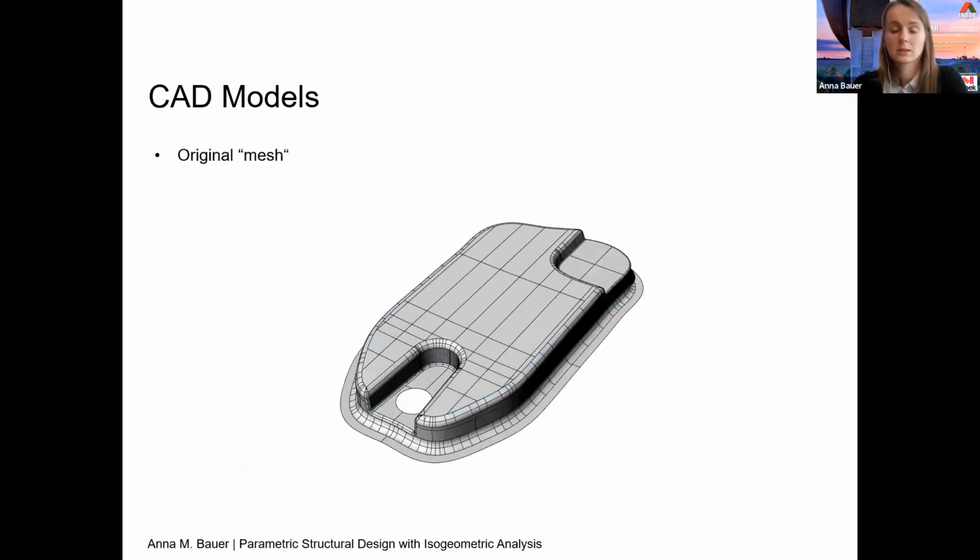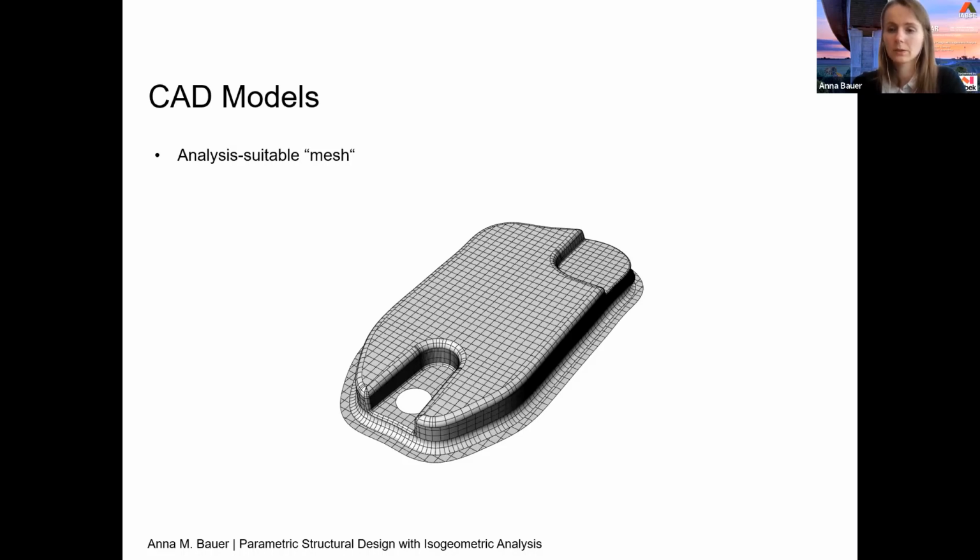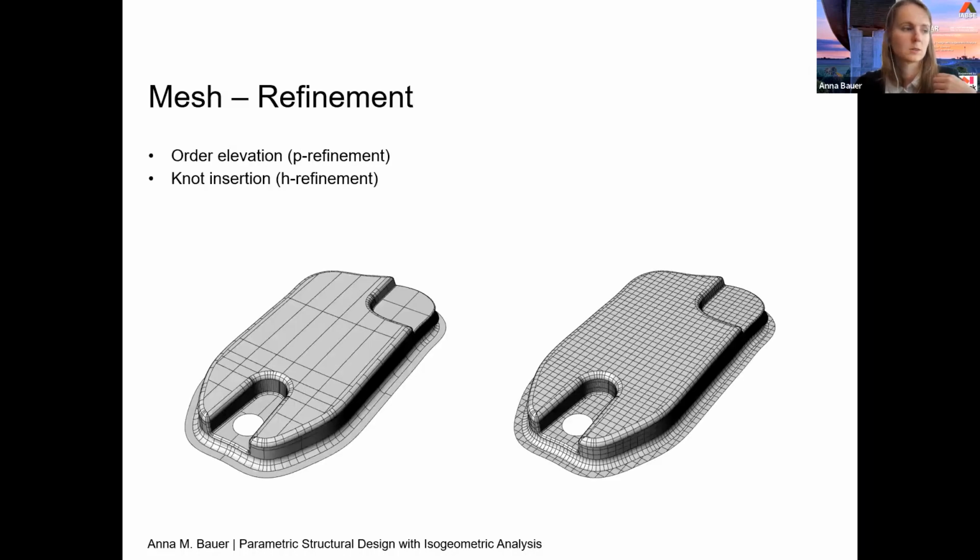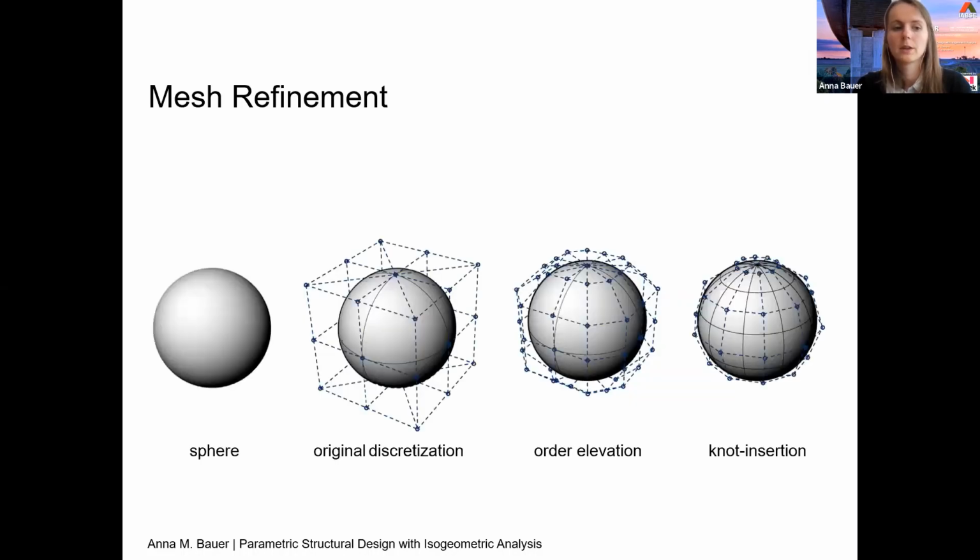And as for classic FEM, it's basically the same. For the analysis quality, it's much better if we have an equalized mesh. Of course we can do the analysis on the distorted one, but the analysis will be better if we have a better mesh. It's the same principle. And here, isogeometric analysis and NURBS provide another really important feature: we can do mesh refinement at every step of our analysis. And while refining the geometry model, we are not changing the shape of the geometry.